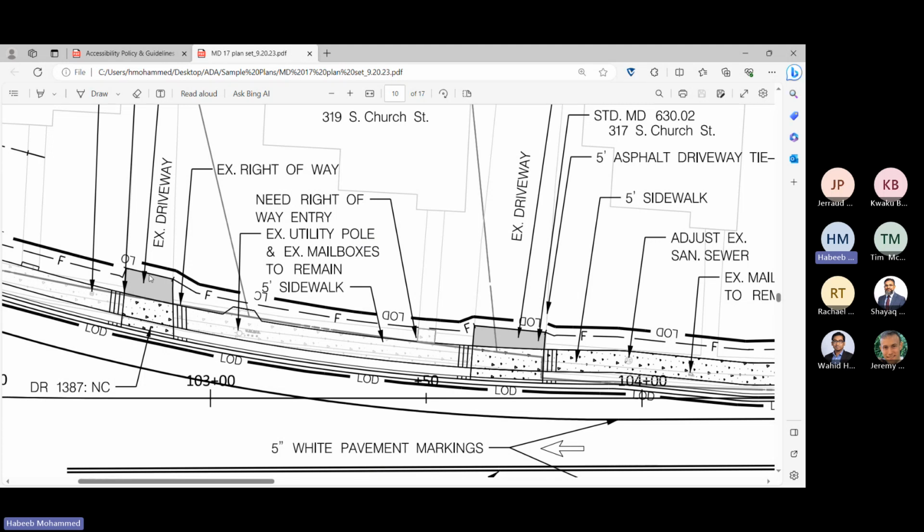So this is a residential, so how about the height of the curb you have here? 6 inch. It should be the 8-inch curb. 8-inch curb, so you are covered here, and then you are going only how many feet? 3 feet flares on both sides. Yes.